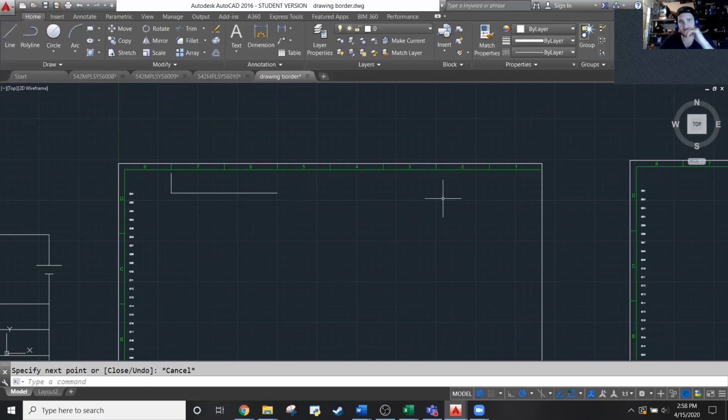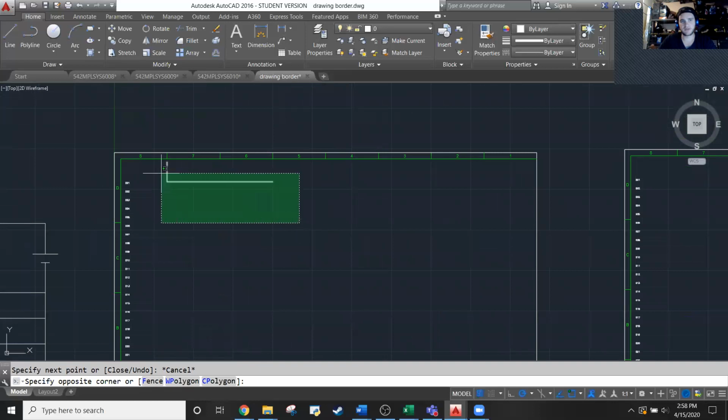All right, now I want to mirror that on the other side of the drawing. So there's a couple ways I could do that, but the way I'm going to do it is with the mirror command. So I'm going to select that, type mirror. And then I know, because there's 8 of these cells, that the middle of the drawing is going to be right here. So at this junction, I'll select that midpoint, move my mouse down, and voila. It recreated that on the other side. Perfect.